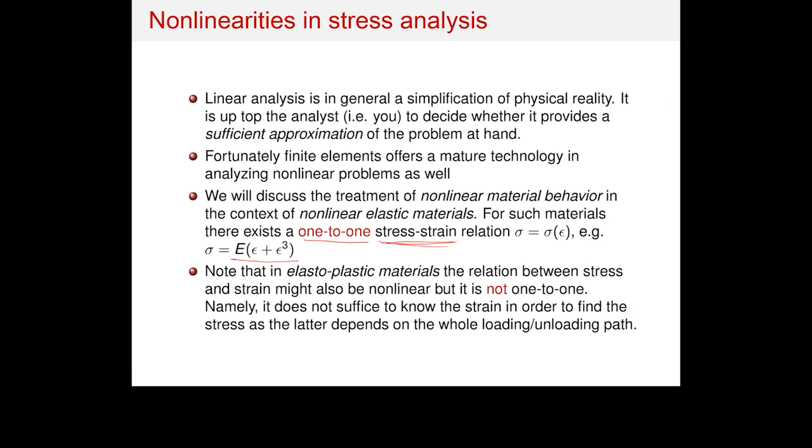Just having the same mesh, the same degrees of freedom, but instead of a linear description of this material you have a nonlinear one, you would easily move from 10 minutes to 10 hours of CPU time. So you can see that this is not quite an efficient way to solve a problem unless you really need to describe nonlinearity in there.